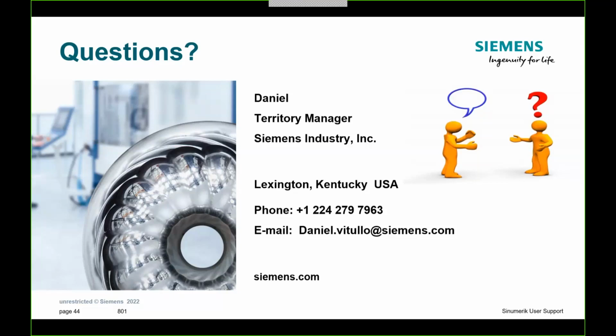Especially when you start talking about the type of advanced machines you see, they're generally a more advanced machine and a little bit higher quality build. So, if you're trying to have milling and turning on a part, and accuracy is important, it's definitely a way to go. If you're trying to eliminate processes, the more you can hold that part from the bottom and get to all 5 sides of it, the better off you're going to be, not just from an accuracy standpoint, but an efficiency standpoint.